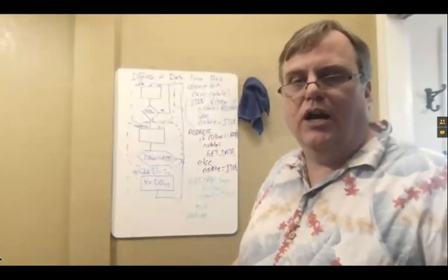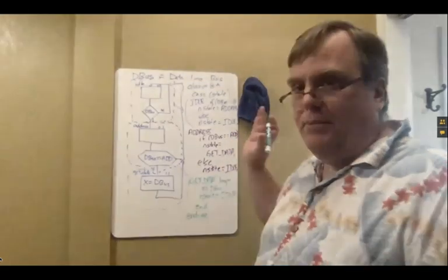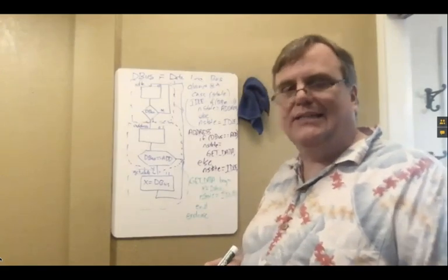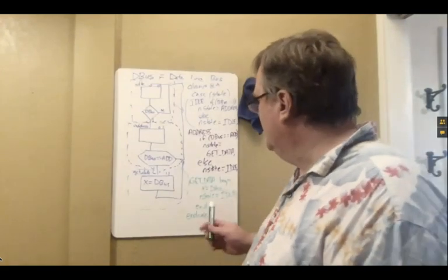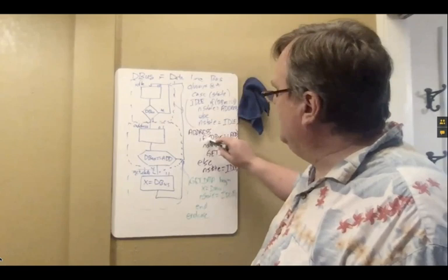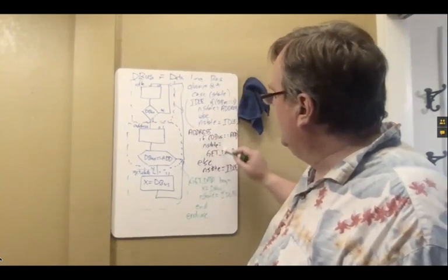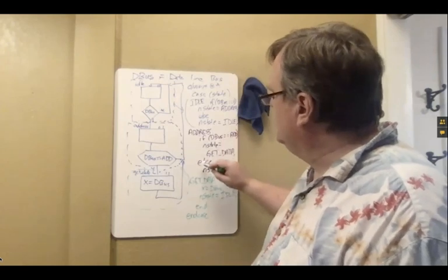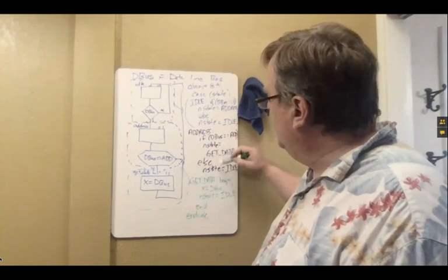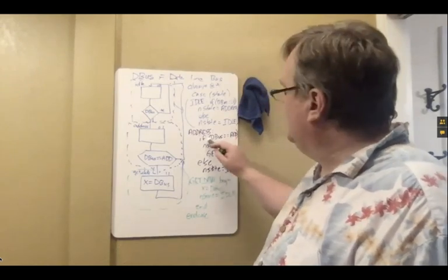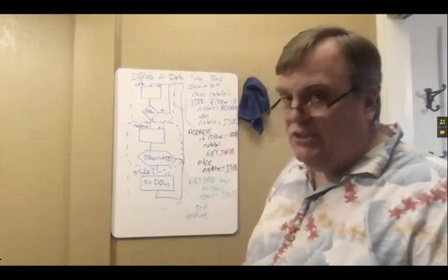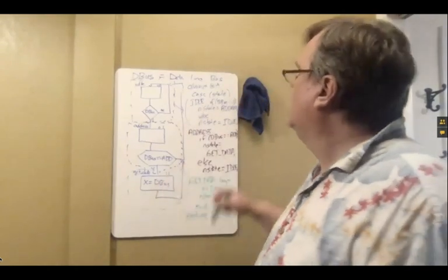That's the convention inside, and Verilog copies C. So that's why I always refer you back to C, so that you start thinking Verilog is much like C, because that's really the idea behind it. So this one has two statements. However, this one has an if statement. And the if statement includes one statement in each clause. So if and else is one thing, and they each get one statement inside there. So if clause gets this, else clause gets this. So this, as big as it is, is technically one statement.